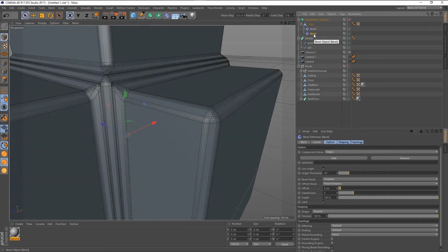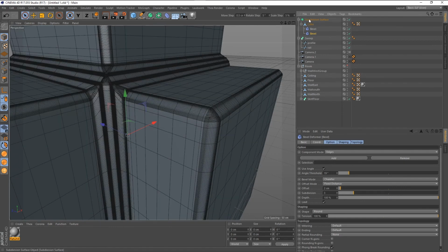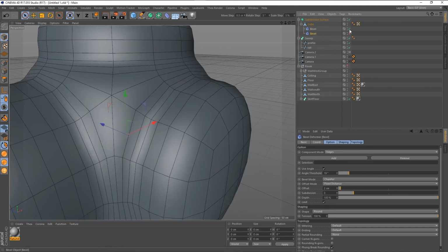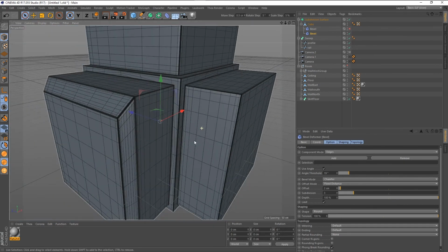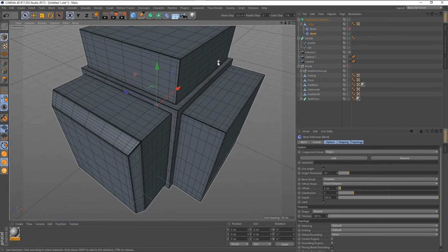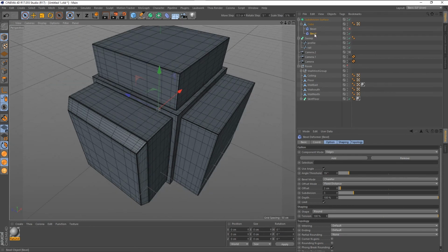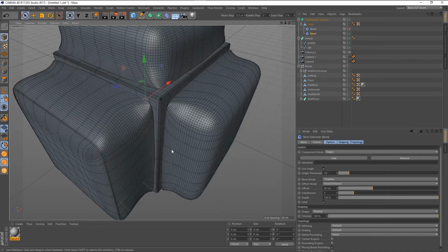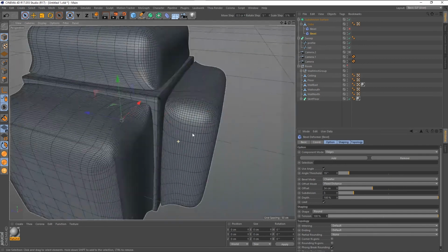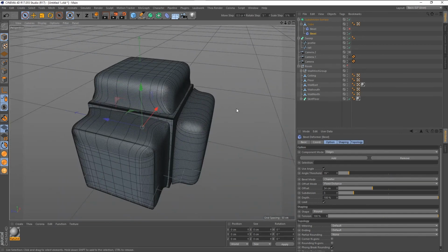And if I hit Q, it'll disable the subdivision surface. So Q only disables those green modifiers. It doesn't disable these blue ones. If you want to disable them, you click on this button here. Okie dokie. Change this one to be that. That is crazy.